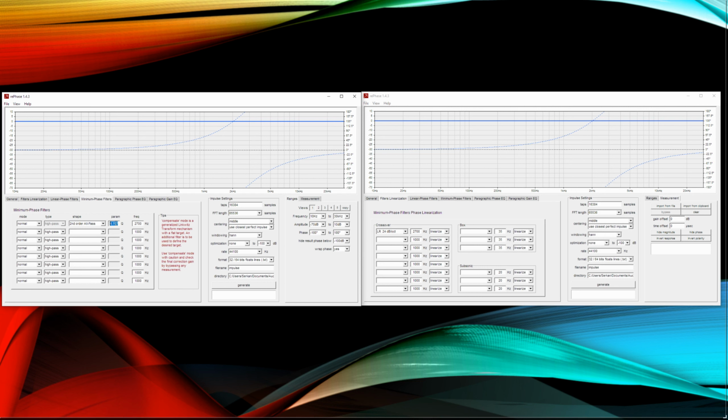This is, by the way, 1 divided by square root of 2, for certain reasons. That's the Linkwitz-Riley constant. When Q is this, it equals the fourth order Linkwitz-Riley. By changing the Q, you can try many different shapes. And again, as we mentioned before, a box filter is nothing other than a second order all pass, fourth order. So let's add this box filter here, low Q 41,